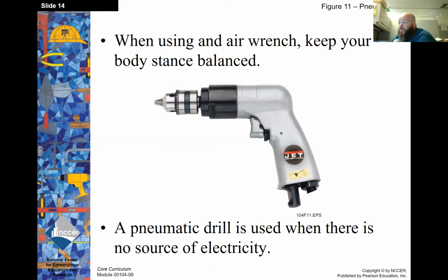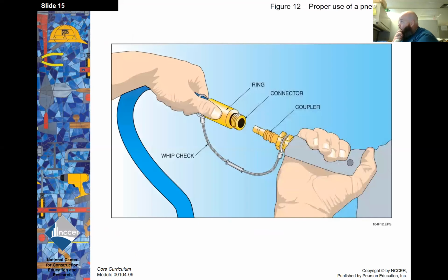The problem is that an electric drill makes so much torque, if the bit sticks, it will just start spinning and can be quite hard to control. Pneumatic drills are very nice because if you get in a bind like that, it'll actually stop the drill motor. They have less torque. They're a lot nicer to use, especially drilling steel with a hand drill.